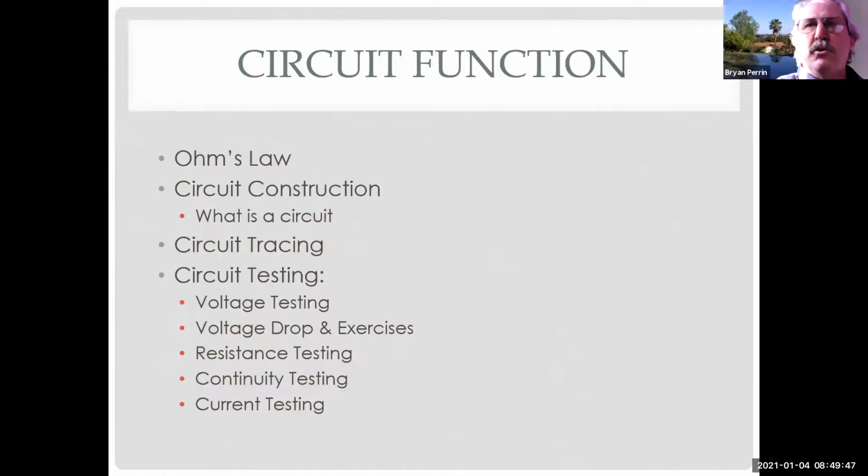So I don't necessarily have to use an ohm meter to measure resistance. I can measure resistance directly, or I can infer resistance by measuring it indirectly. And what we do in industry is we measure it indirectly most of the time, because it's more accurate and it's more efficient.